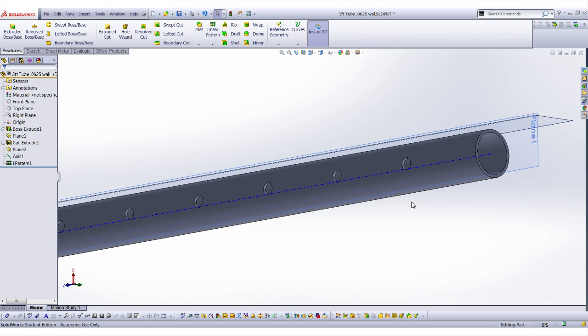What that basically means is somewhere you have a line that isn't a closed shape. So you just have a line somewhere in your sketch. Right, but in this case, you did not put it for construction. He thought he had a construction line, but he didn't. So there's a pretty easy solution. By making that line construction, we'll most certainly be able to fix it. And it works.